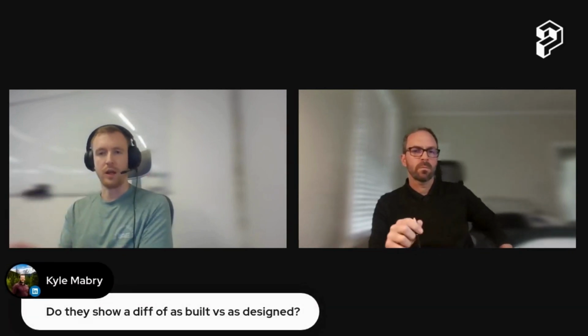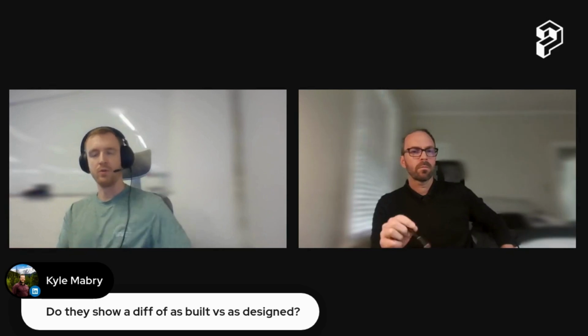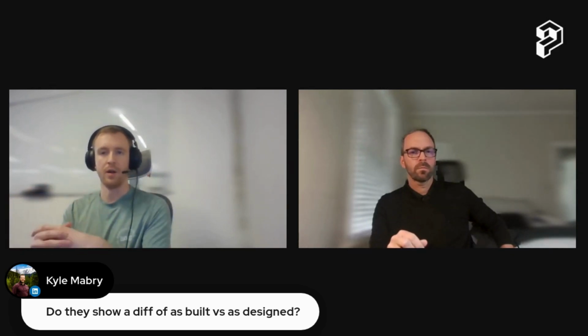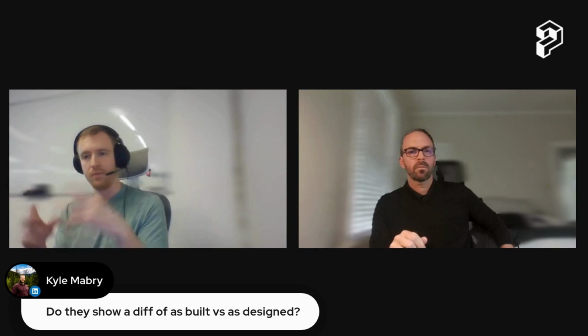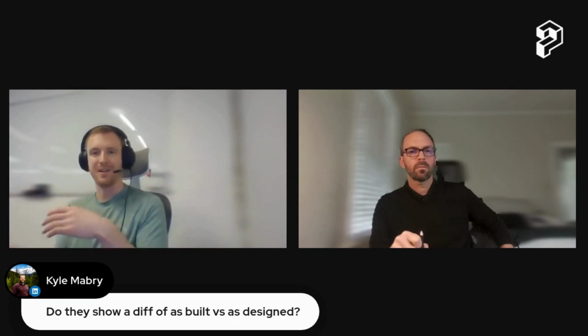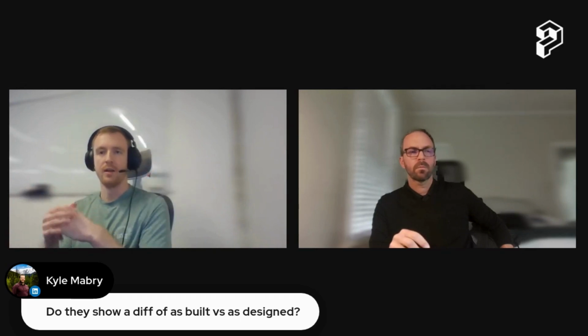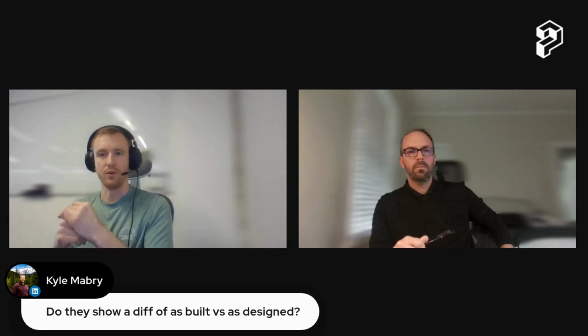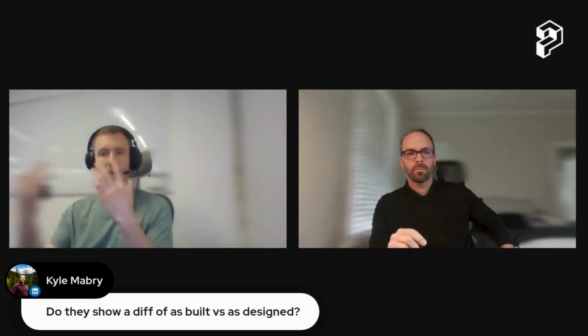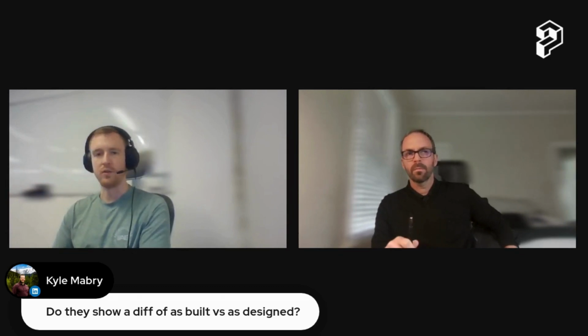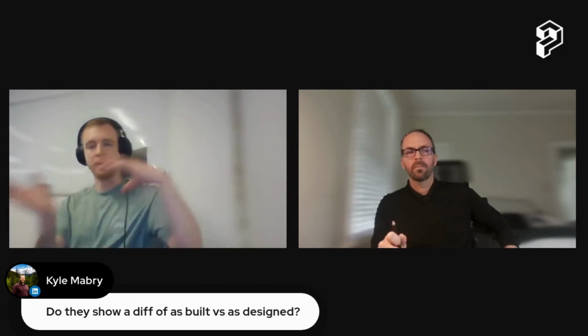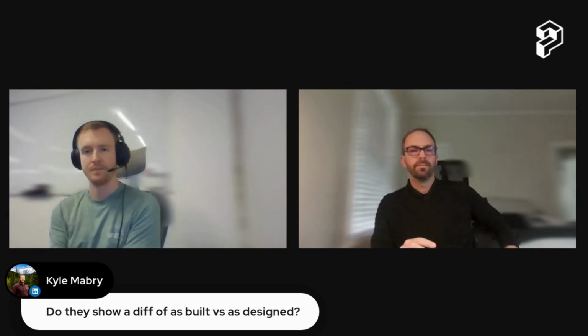There's also a question from Carl regarding whether they show a diff between as built and as design. Currently within the Revit plugin, it's not there at the moment, but inside Reality Plan, we do have a tool to do such a visual compare. So you can bring back the as design and compare it against the scan and see the deviations visually. We have some visual effects that allow you to see such differences. So that's a tool that we have inside Reality Plan. It's not yet exposed on the Revit side, I would say.